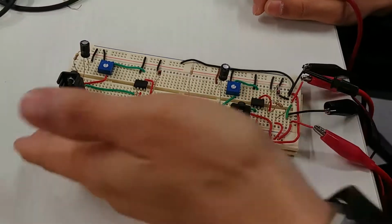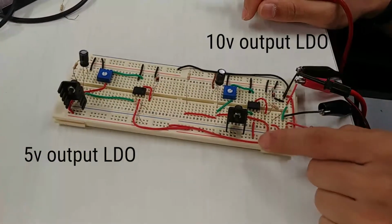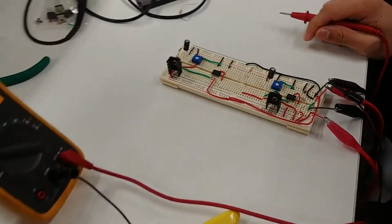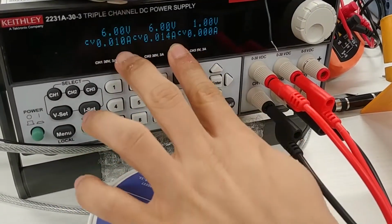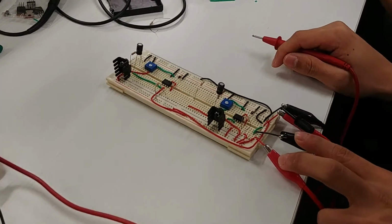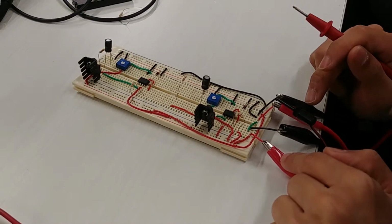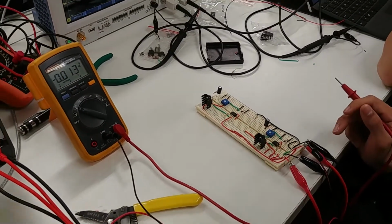So this is the circuit for our LDOs. We have two separate circuits, one from 12 to 10, and this is from 6 to 5. If you take a look at the power supply, we have two power supplies in series, 6 volts each. The first power supply is here to here, 6 volts, and the second power supply is here to here, 6 volts. So across this whole thing here is 12 volts. Now I'm going to turn it on and do a demonstration.